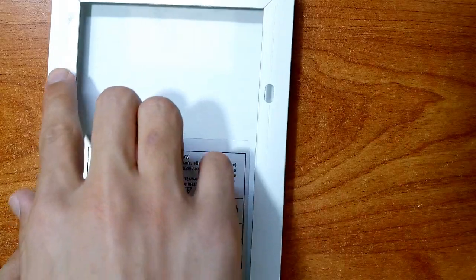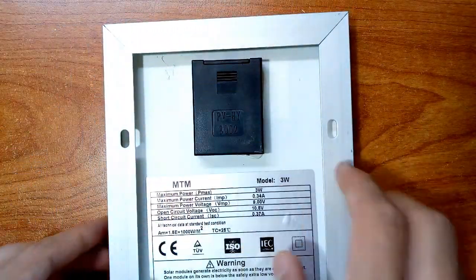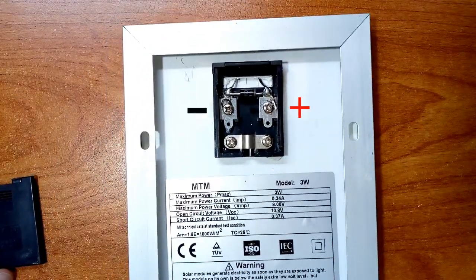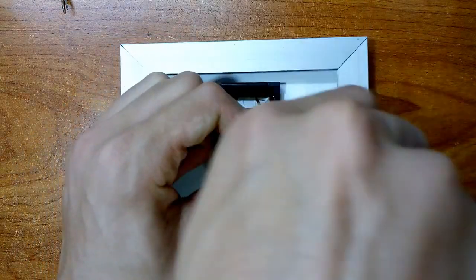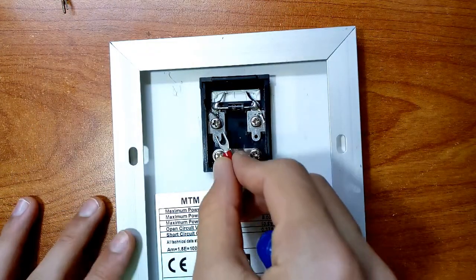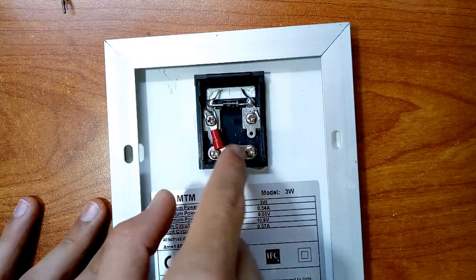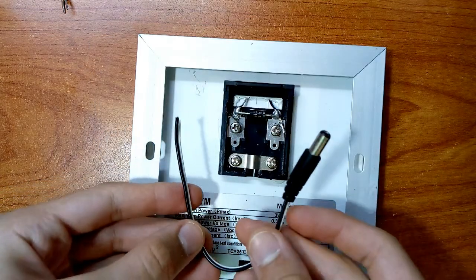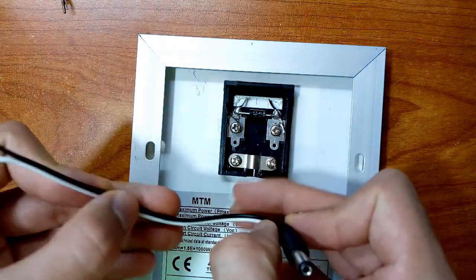Also, solar panels can be easily mounted as they have holes to attach to a wall or something like that. Solar panels also have a black box where you can attach all the wires and everything inside, so it looks more professional and better in the design. In normal conditions, you would attach the wire to the bolts like this with this connector, but because the black box is very small and the solar panel itself is very small, I would just connect the DC male wire directly into the bolts and just screw it in place.